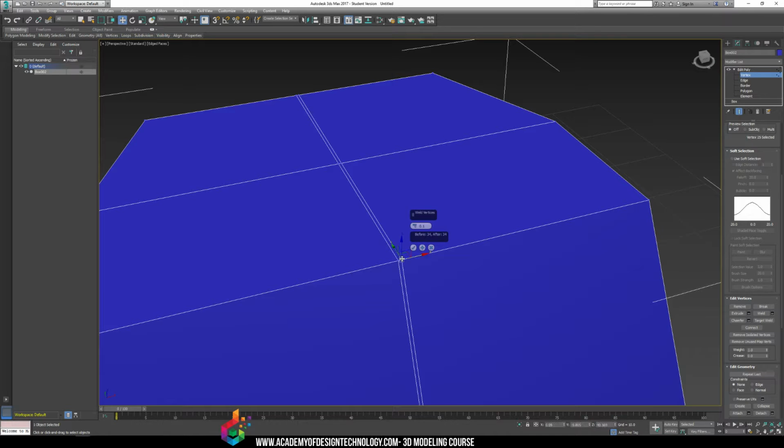I grab the two vertexes, or even more vertexes that I want, like so. These three rows up top here. And you'll notice that there's no preview of it welding. This tool, Weld Vertices, allows us to preview what's going to weld. And currently at 0.1, nothing is going to weld. It says before there are 34 vertices, and afterwards there's 34 vertices, which means nothing is welding.